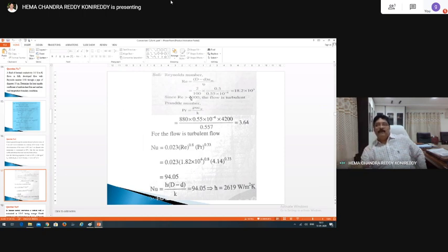So, therefore, fluid should be heating, and therefore, please make a correction here. It should be 0.4 for heating, not 0.3. It can take either 0.3 or 0.4. So, you should use 0.4 here. I'm sorry for this. So now you calculate Nusselt number. Nu is equal to hL by k, where characteristic dimension is D minus d, and therefore you calculate what is the heat transfer coefficient.